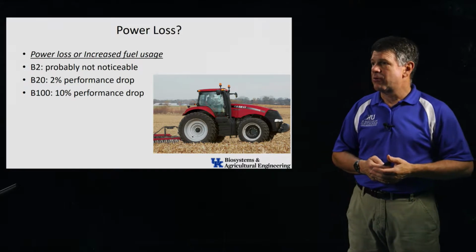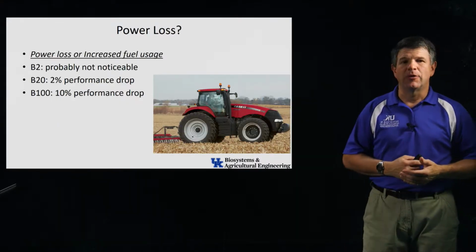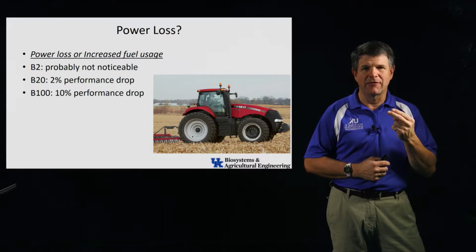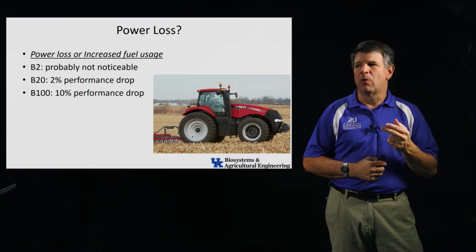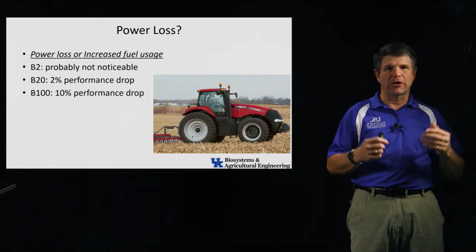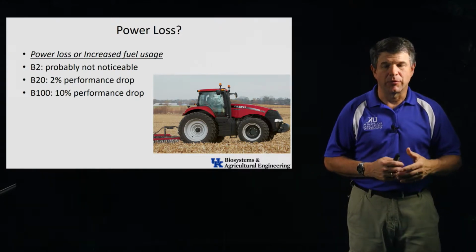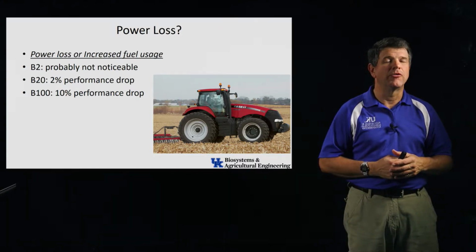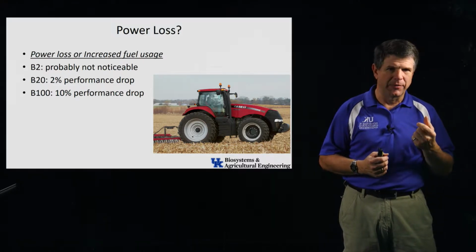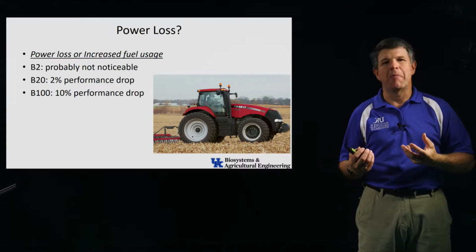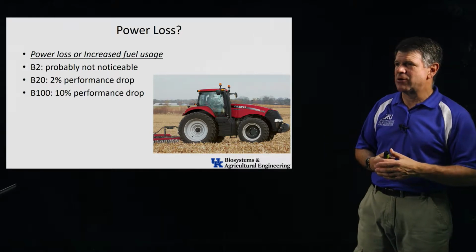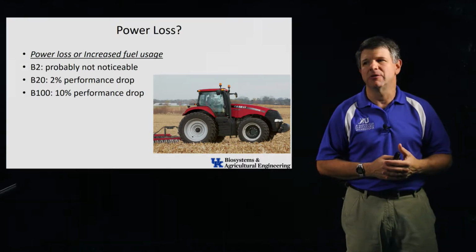So what effects does it have on our performance? Well, there are two ways that this could manifest itself. It can either manifest itself as a power loss or as increased fuel usage. So if I'm a farmer with a tractor out in the field, or a truck driver putting diesel fuel in an over-the-road truck or something like that, what's going to happen if I go from a petroleum-based diesel to a biodiesel? So what am I going to notice? And this table kind of shows you a little bit, hey, if I just got a 2%, I'm not going to notice anything.